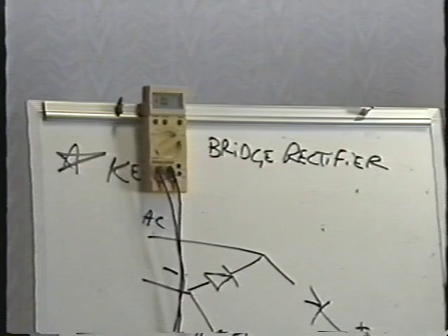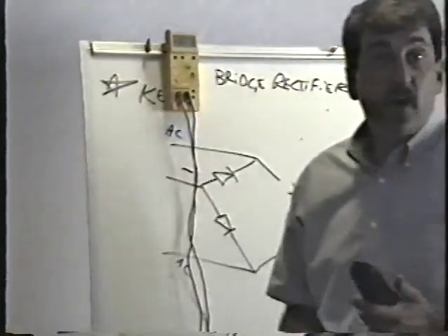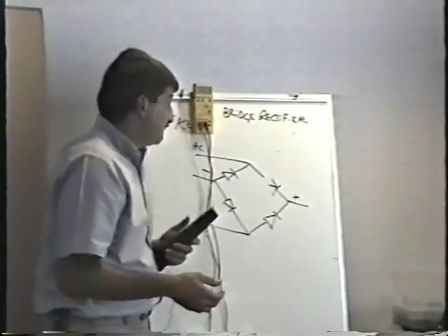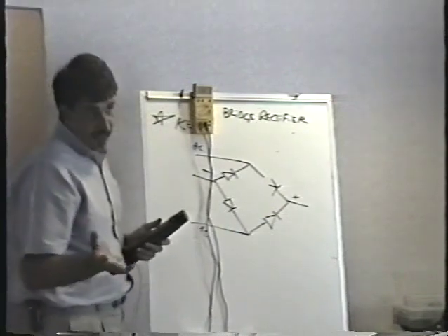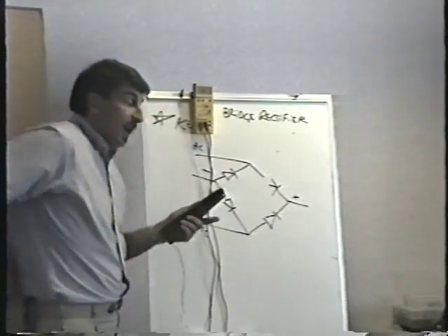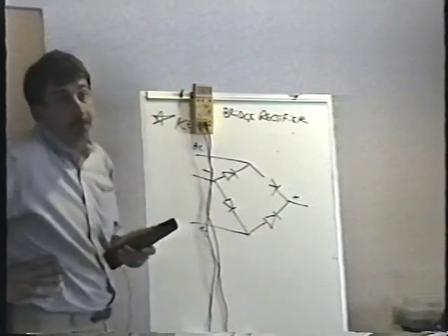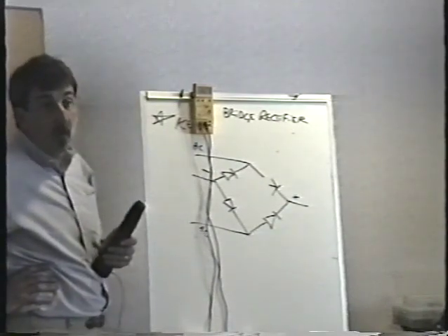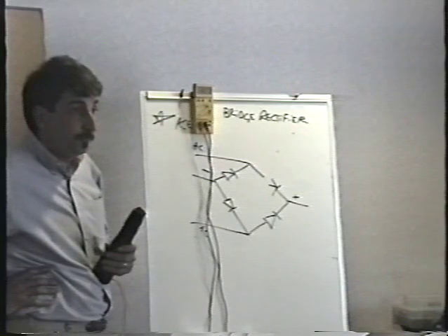So as far as diagnosing bad bridge rectifiers is concerned, it should not be a problem. It's pretty obvious. It's very unusual to have an open circuit. Almost always they short circuit, like the first one I showed you.